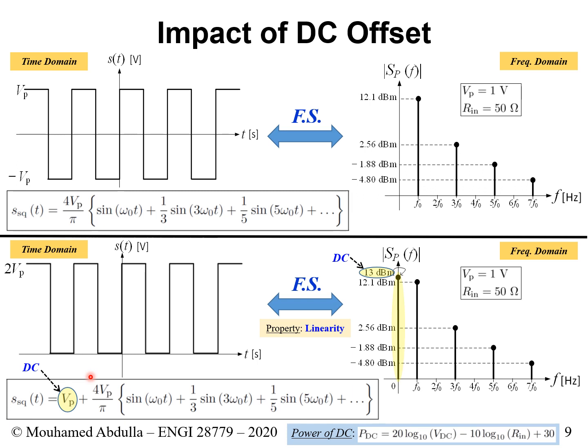Analytically, one way to do this is to simply use the Fourier series expansion, right? So basically, you know the formula. Fourier series is A0 divided by 2 plus the summation of AK cosine of the generic harmonics plus BK sine of the generic harmonics, and then you go through the analysis, and if you get anything for A0, that's your DC component.